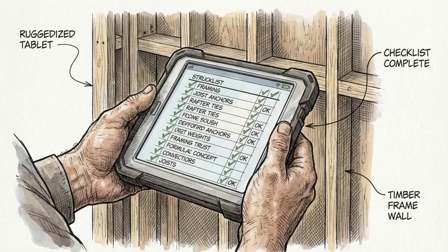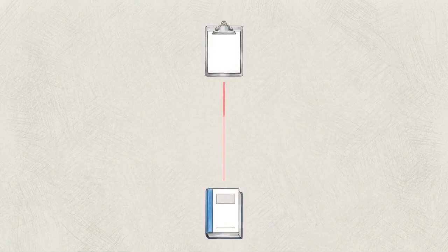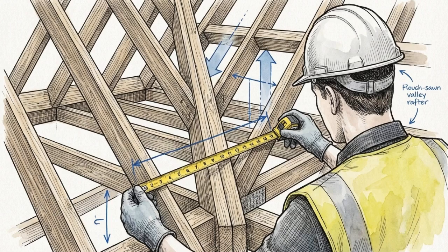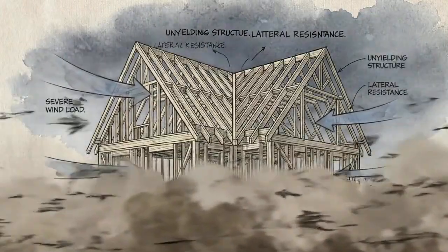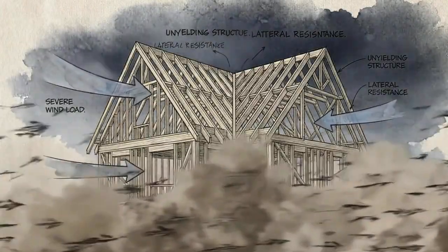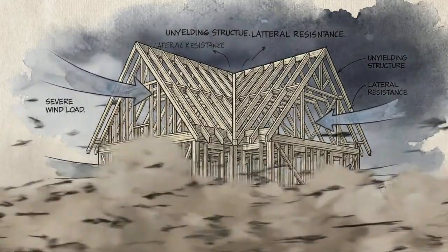Supervisors can proactively manage these risks by using existing inspection data to improve on-site outcomes. Reviewing certifier inspection reports and cross-referencing defects back to their specific clauses helps identify and correct common failure points. Use your site walks to explicitly verify at least one specific clause against the standard. AS 1684.2 provides the technical roadmap for building frames that resist physical forces and maintain the builder's legal compliance.